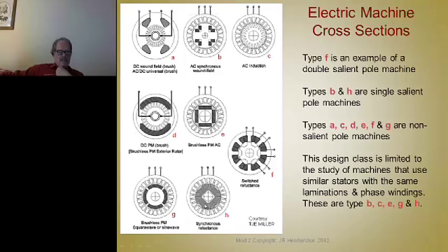So if this is a direct axis, the inductance of the phase windings in this axis is high because there's lots of iron in the circuit. But in quadrature, or 90 electrical degrees, this is a 4-pole machine, so it's 45 degrees mechanical. This is the quadrature axis, so the inductance of the phase is low in that axis because there are a lot of flux barriers radially from the shaft out in that quadrature direction, you see.